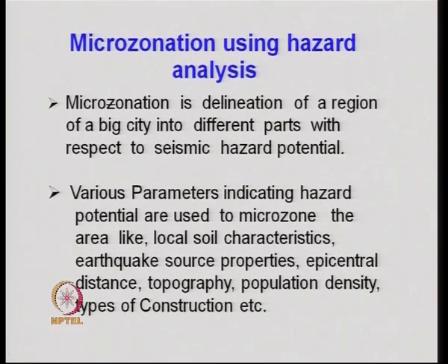Next we come to a very important topic, the microzonation using the hazard analysis. Microzonation is a very useful concept for mitigating earthquake disaster in a particular region, and for that one should have a map for the region showing the relative vulnerability of the different sub-regions in that particular area.